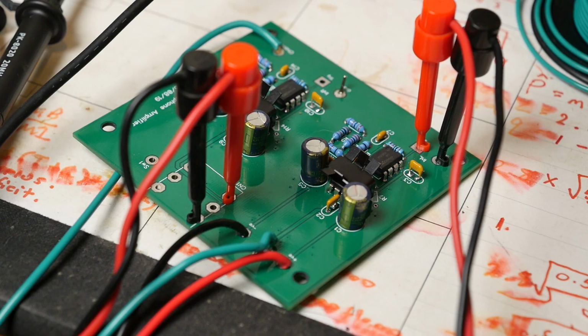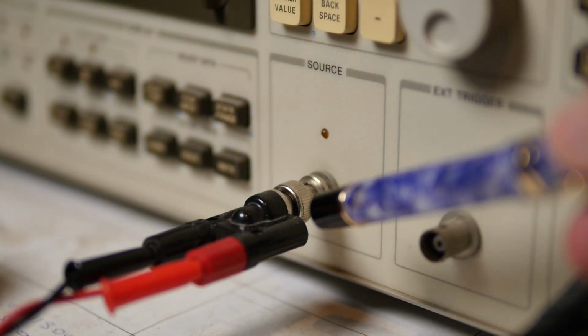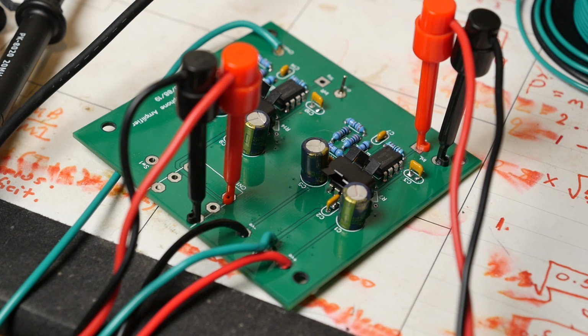What we'll do is we'll make some measurements of the output of the error amplifier itself. And from that, we should be able to infer some things about the behavior of the system as a whole. So let's give it a go. So we have the headphone amplifier powered up on the bench. The left channel input here is connected to the source output of our dynamic signal analyzer, and the main output here is connected to our audio analyzer.